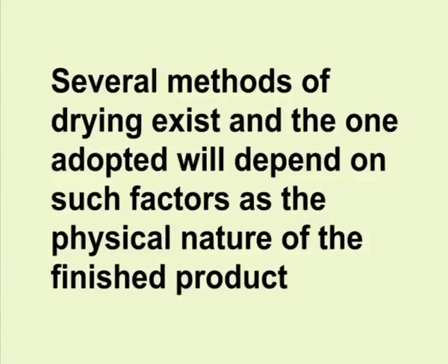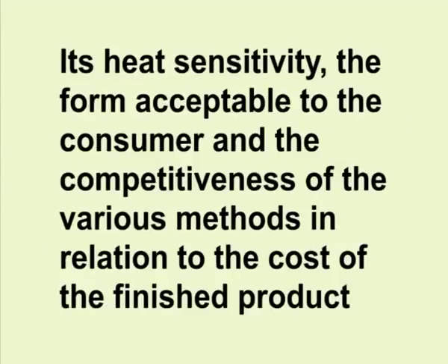Drying. Drying consists of liquid removal, either organic solvent or water, from wet crystals such as was described above, from a solution, or from solids or cells isolated from the very earliest operation. Several methods of drying exist, and the one adopted will depend on such factors as the physical nature of the finished product, its heat sensitivity, the form acceptable to the consumer, and the competitiveness of the various methods in relation to the cost of the finished product.